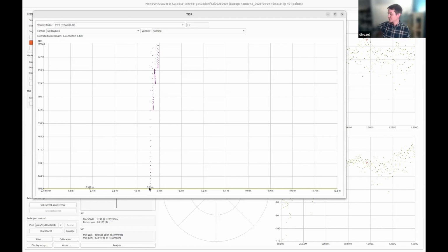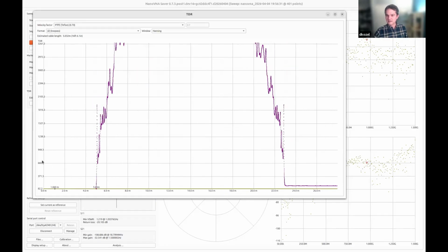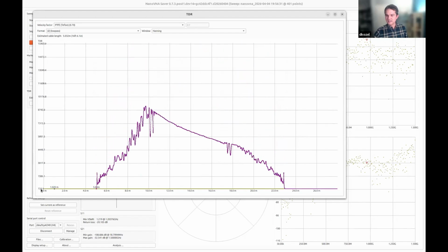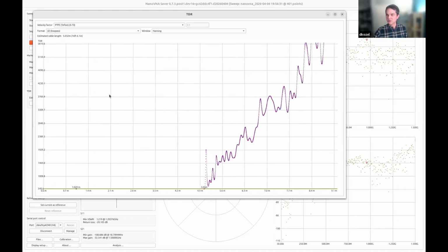Yes, I did. It is currently just left unconnected. And so we can see that at 5 meters distance, the impedance is going off into infinity. It's an open circuit. This is what we're expecting. If I crimped the connector really hard at some point, we would see that impedance would either drop up or down. Terrible plots.